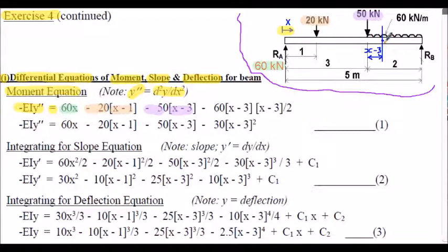But also now I have a bending moment generated by the UDL. So I have 60 kilonewtons per meter. Again, it's a negative bending moment, negative 60. That's multiplied by the x minus 3 at this particular position here. X minus 3 would be the distance of the UDL. And don't forget the total load of that piece of UDL here will act halfway along the x minus 3. This distance here is the x minus 3 divided by 2.